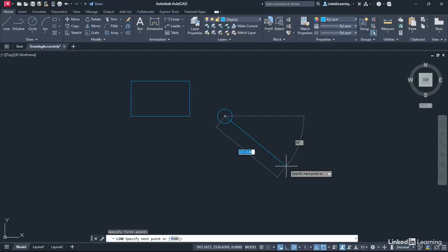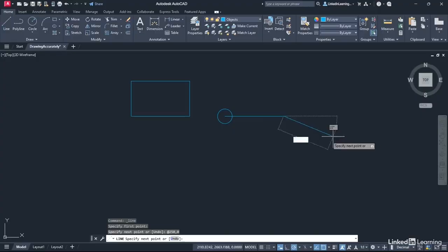We're going to type the @ symbol. So I'm going to type @ like so. Can you see that appears on the dynamic input entry like so? And we need that to be 250 long along the x-axis, but 0 going vertically on the y-axis. So we're going to type in 250, comma 0. Now that line will now go to the right because it's positive, and it will be horizontal because the y value is 0. Press enter, even though the line looks a bit weird, and you'll see there's your 250 long line. And now we're ready to come off of that segment there.